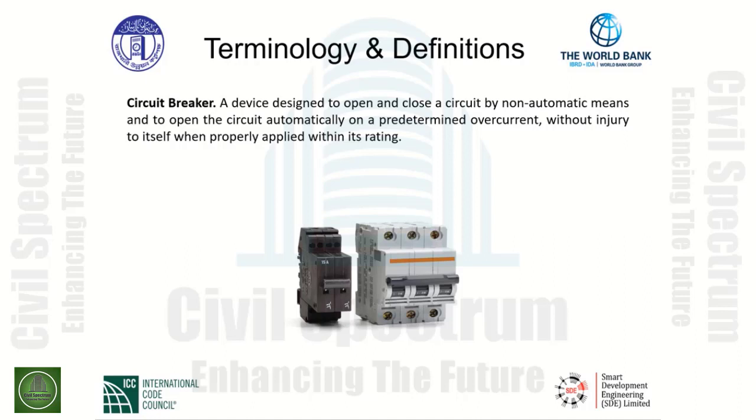Circuit breakers are designed to open the circuit on an ampere rating that would exceed the conductor rating in most cases. Therefore, this is a protection method that we have to have in place for feeder circuits, branch circuits, and subfeed circuits as well.